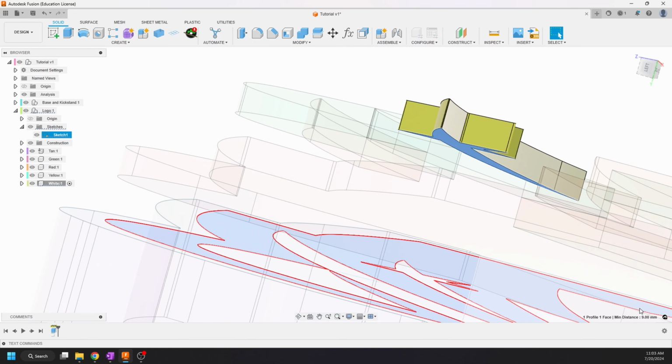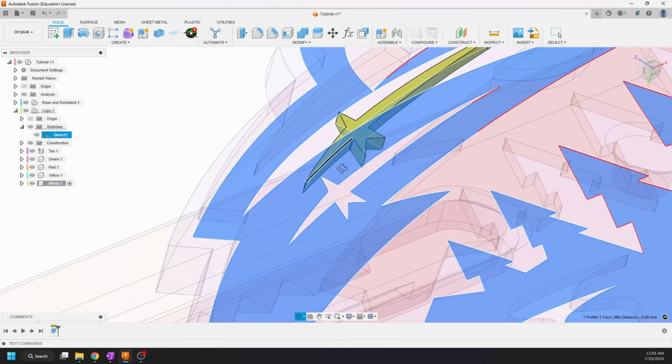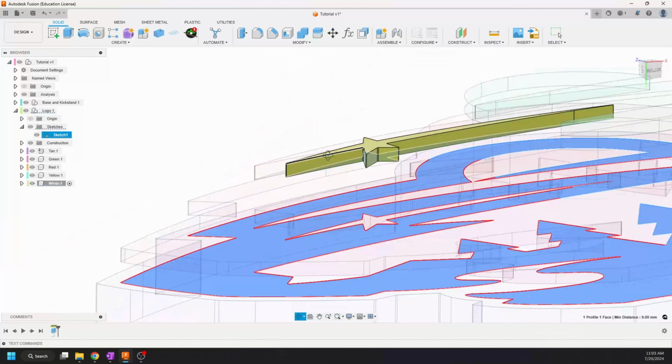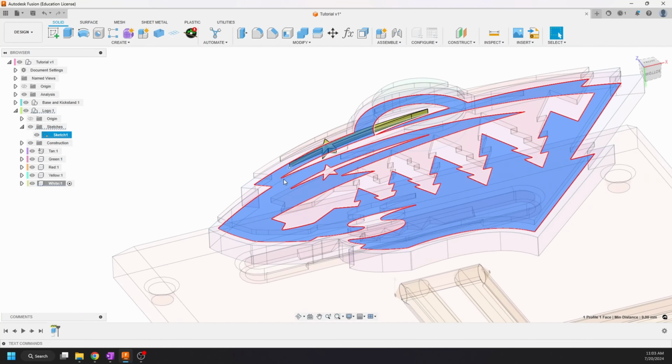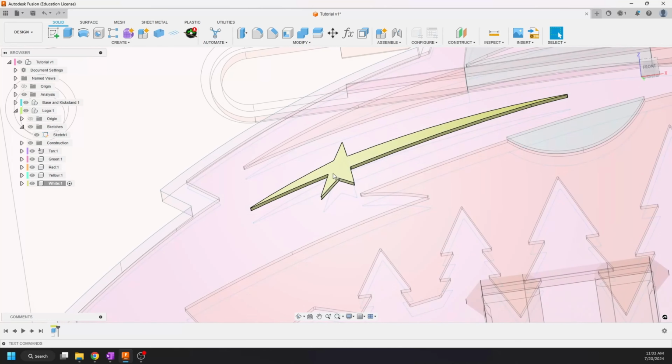So 9 millimeters plus 4 is going to be 13. So we will make the pin 13. And you can see this one is probably going to be a little small to have a regular pin, because since the pins are circular, you need to have at least 2 to prevent this part from spinning, right?